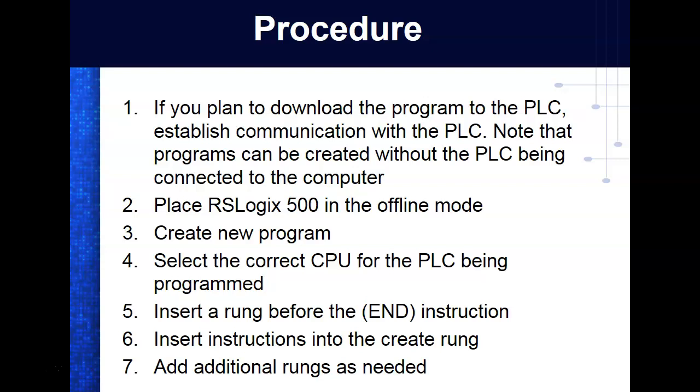So the PLC's got three modes we can operate in. We can operate it in the run mode. So when you switch it to the run mode, you can't put anything there. It's running your program. We can put it in the program mode. The program mode is where we can upload or download programs. And then on all these new PLCs, we have what we call the remote mode, which is what ours is. Remote means your application switches the PLC between those other two modes.